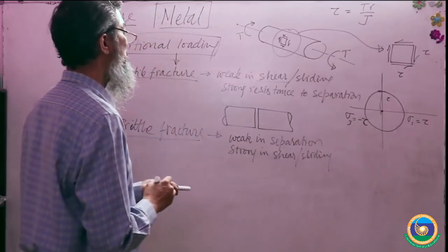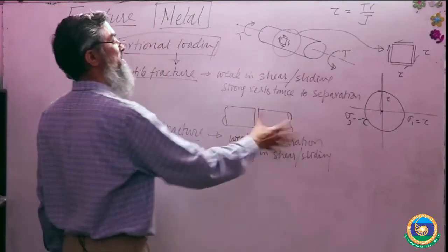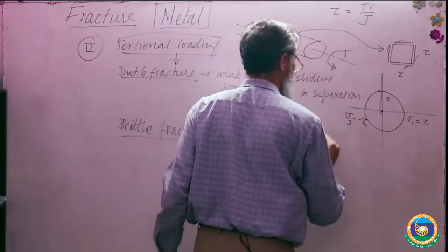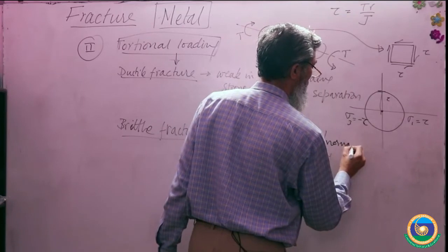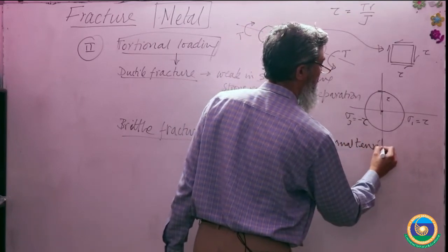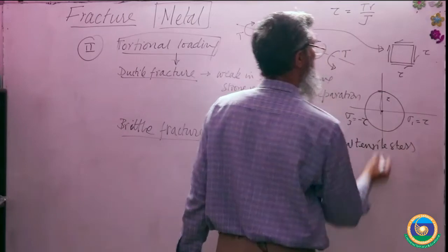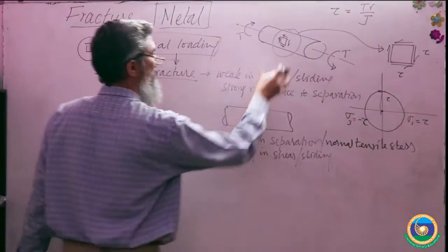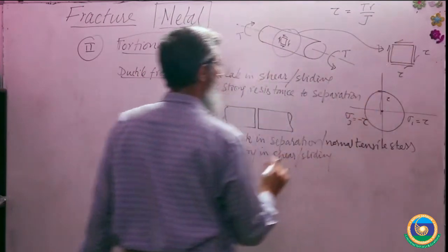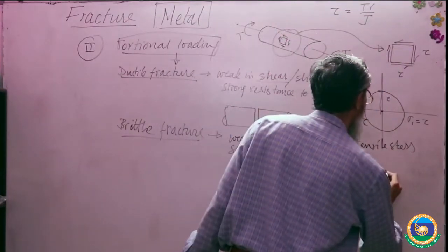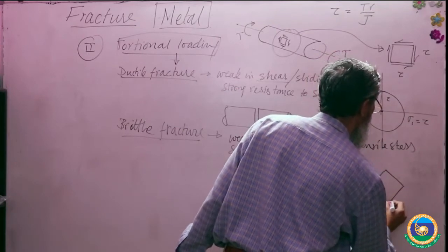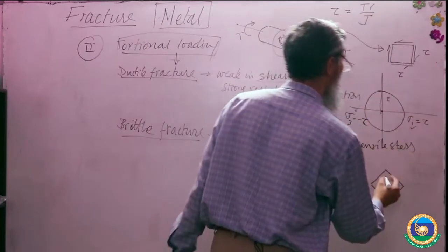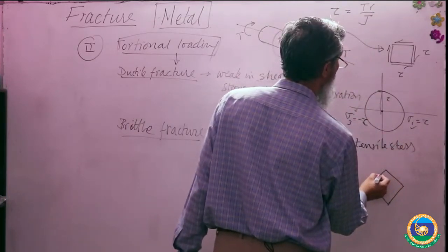We are not now interested in shear stress, we are interested in normal stress. Separation means normal tensile stress. In this case we know that it is at 45 degrees, and if you rotate this element by 45 degrees, you will get these values like this.